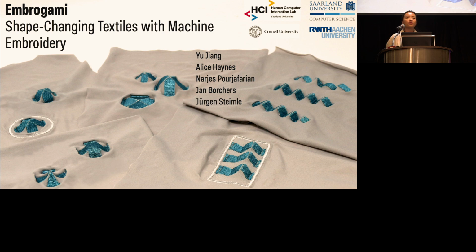I think the only electronics-based actuation we tried is SMA because it's the most lightweight and small actuation method that we have at the lab, which is also quite easy to integrate into the textile directly. And with the very thin SMA that we used, it was also very safe for human skin or on the clothing. And I think one drawback is that it is quite slow to actuate. I think it would be future work to try other possible actuation methods, but we didn't try. But I think one benefit of Embrogami is it's compatible with other existing e-textiles, so feel free to try other things yourself with our structures.